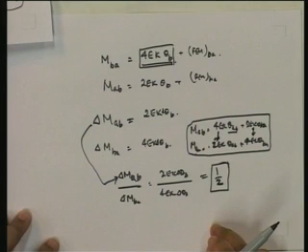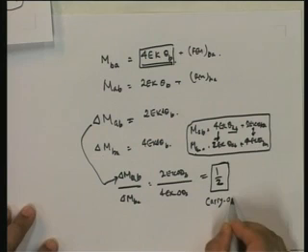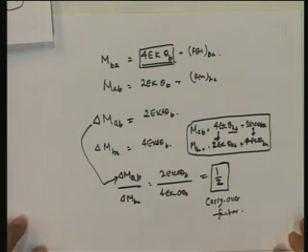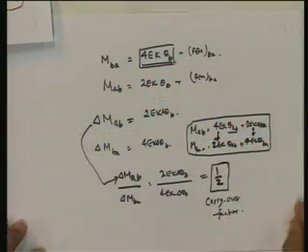This is the carryover factor, and for a uniform beam, this happens to be equal to half. Now note that if you transfer a moment to a fixed end, remember that you do not release a fixed end. So there is no carryover from the fixed end to the other end. It is only when you release that you generate this carryover.